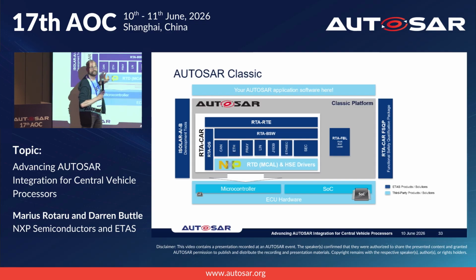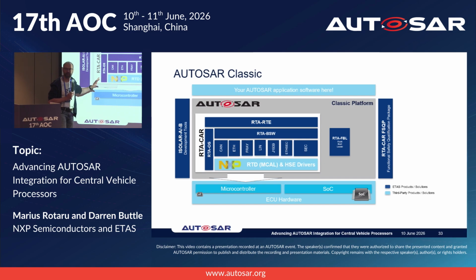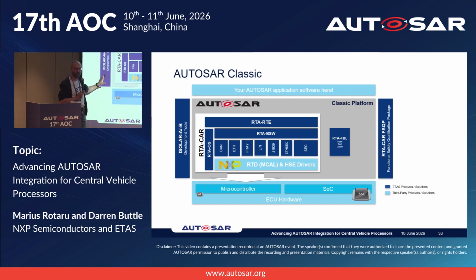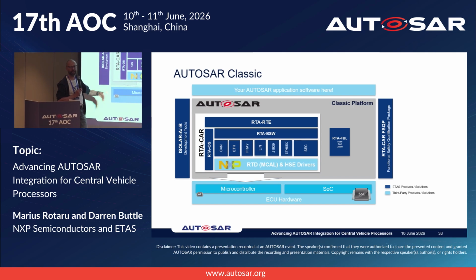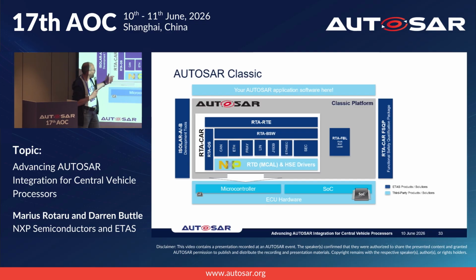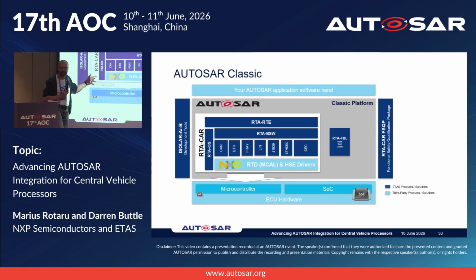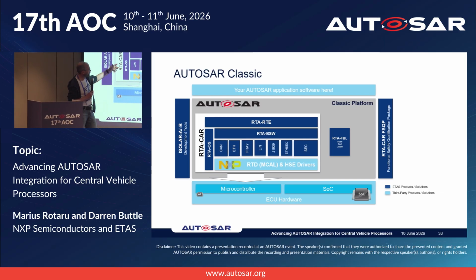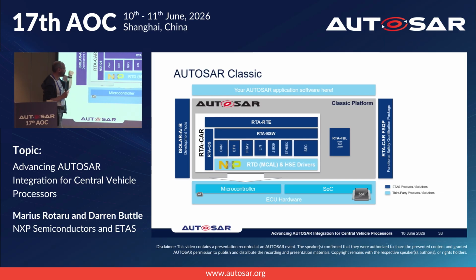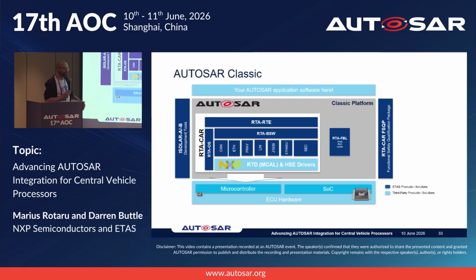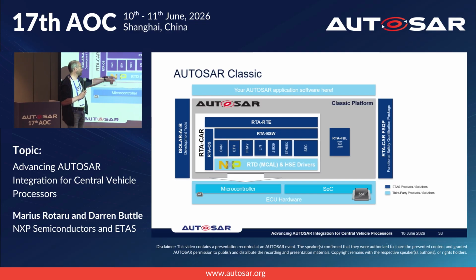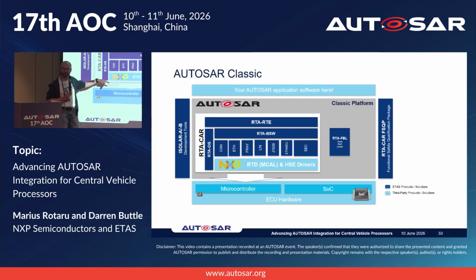All of this stuff stays exactly the same because we don't need to worry about that, because it's just standard software. We just need to compile it and relink it for the chip. And then the vast majority of the magic is down here in the software drivers from NXP. So we've got the standard things like the Ethernet interface talking to the Ethernet driver down here, and the CAN interface talking to the CAN LLC driver.